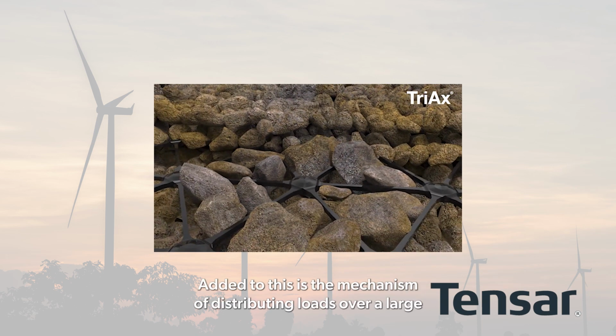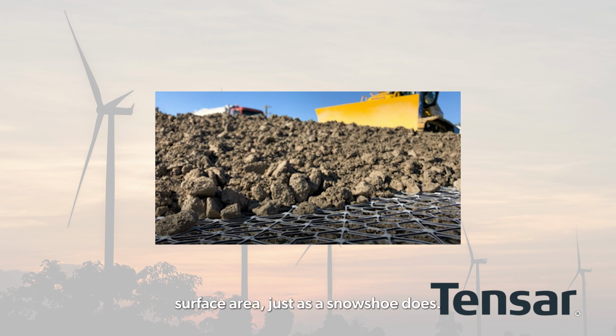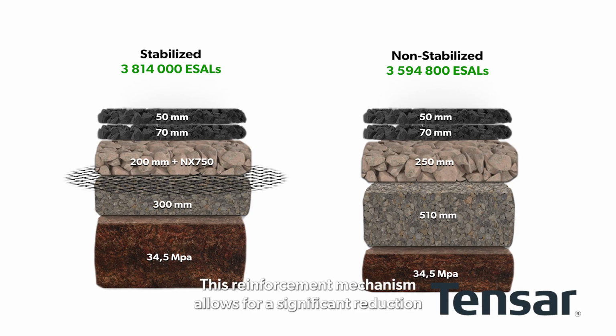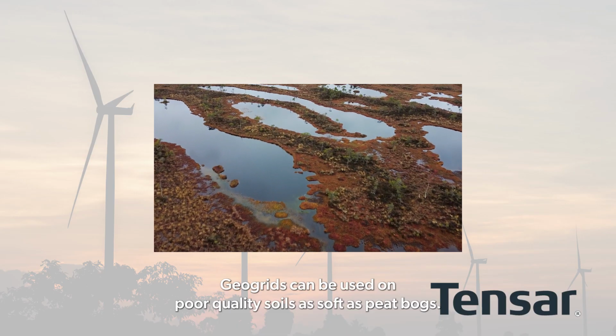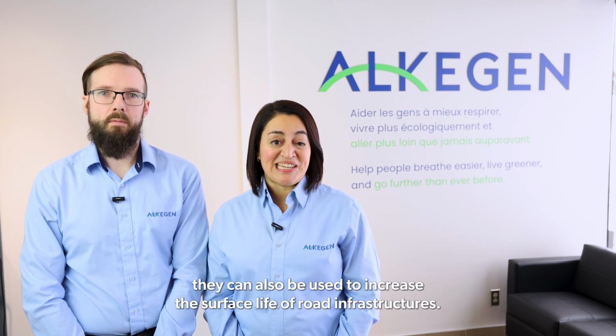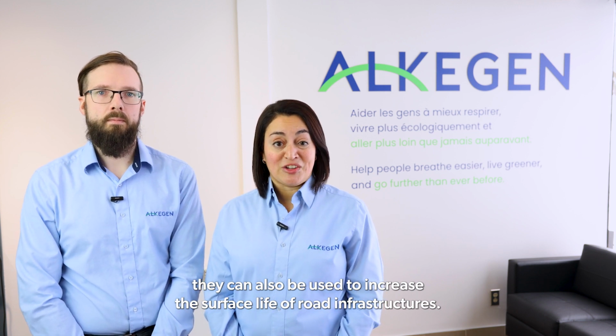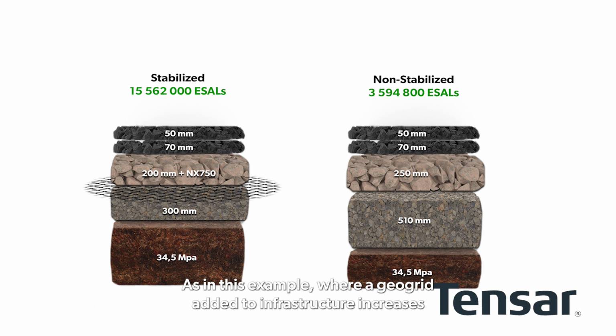Added to this is a mechanism of distributing loads over a large surface area, just as a snowshoe does. This reinforcement mechanism allows a significant reduction in granular material for equivalent performance. Geogrid can be used on poor quality soils as soft as peat bogs. Geogrid not only reduces the amount of backfill used, it can also be used to increase the service life of road infrastructures. As in this example, where a geogrid added to infrastructure increases the service life of this asphalt pavement